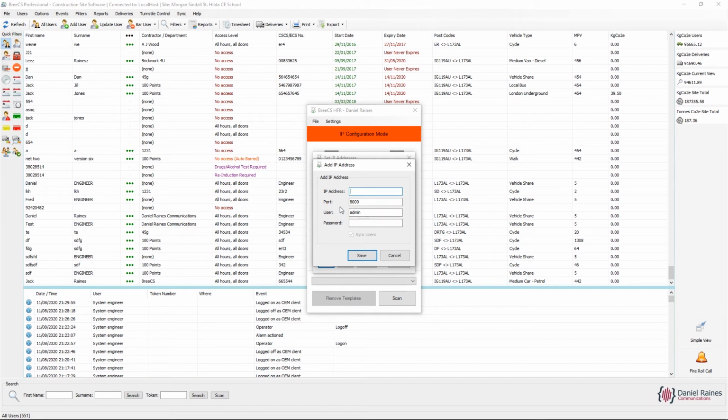I believe the default IP was 192.168.0.64, I think it was, but off camera I changed that to meet my network settings here. So in this example, I've set the device with DHCP turned off, as in a static IP address of 192.168.0.24, but again that will be whatever suits your network requirements. The port will remain 8000.